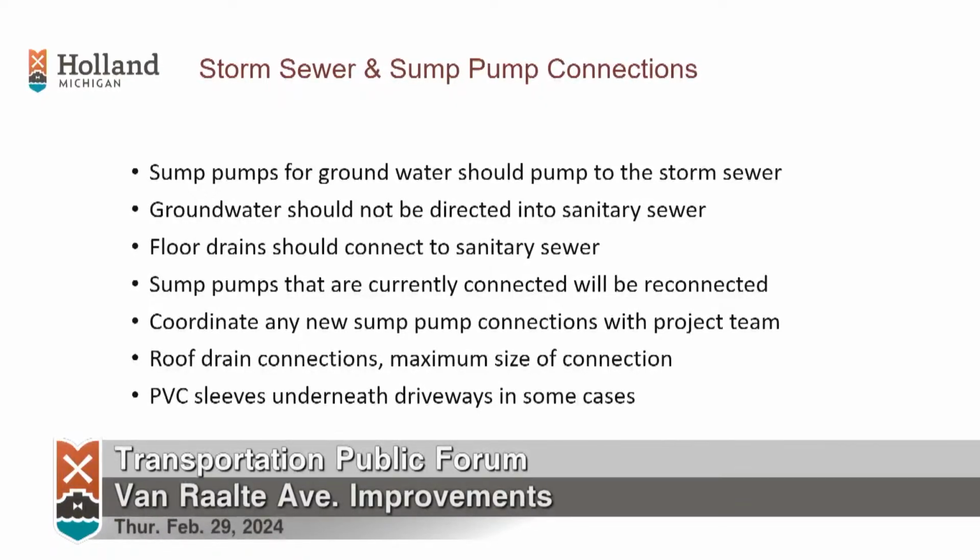We do intend to install PVC sleeves, typically 4-inch sleeves underneath driveways, so that if there is a sump pump connection, we typically don't allow folks to blind tap those into the side of a pipe. We typically want those all connected into the nearest catch basin along the curb line. And so that's where you can thread those.